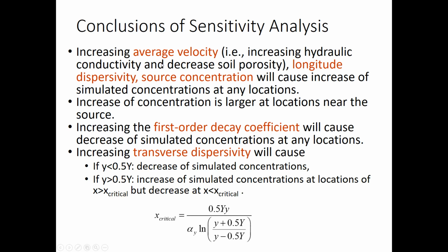And so these are the conclusions we made for the sensitivity analysis. If you increase the velocity, longitudinal dispersivity and the source plane concentration, your simulated concentration will increase.